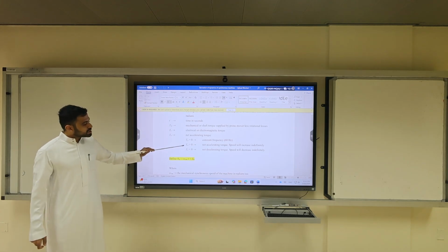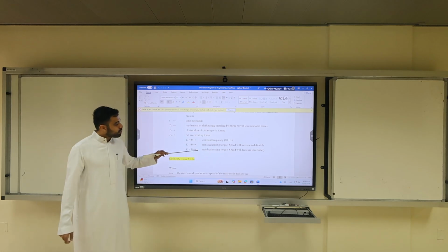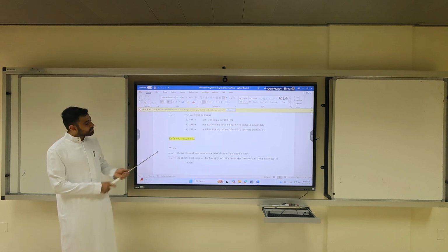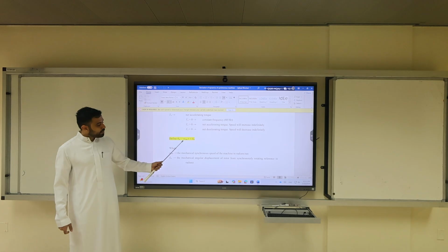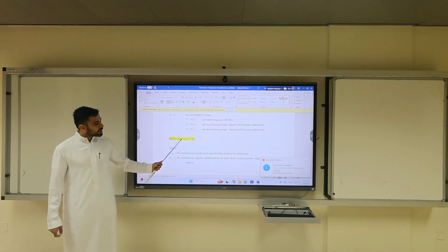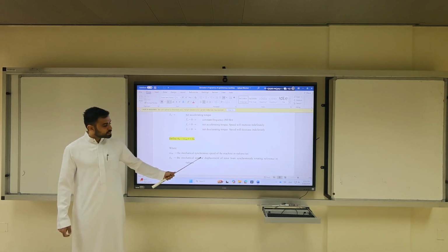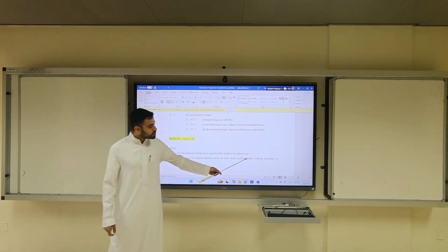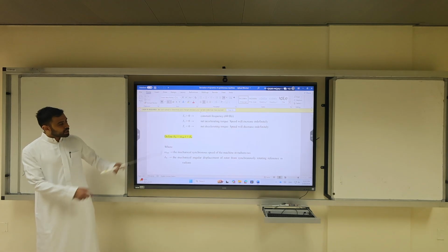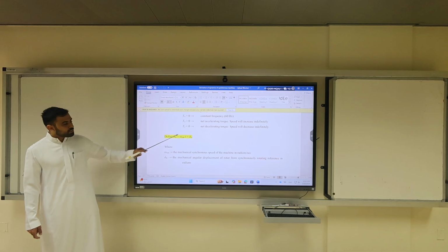So when the torque, the acceleration torque is positive, net accelerating torque, speed will increase indefinitely. When the net decelerating torque, speed will decrease indefinitely. So define theta M to be omega Sm, which is synchronous speed of the machine in radian per second, times t, plus some delta M, which is the mechanical angular displacement of the rotor from synchronously rotating reference in radian. This is another quantity. So theta would change over time. At time 0, theta m is delta m.